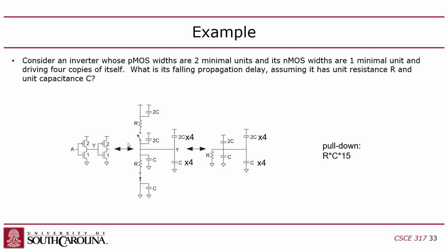And you can calculate the FO4 delay if, of course, you know what that capacitance and unit resistance is. So in this case, this is again pull down, so everything is the same as the previous example. The only difference is that all the gates are the same size, but because I'm driving 4 inverters, the only thing you have to adjust as compared to the last example is the gate capacitance on the output.